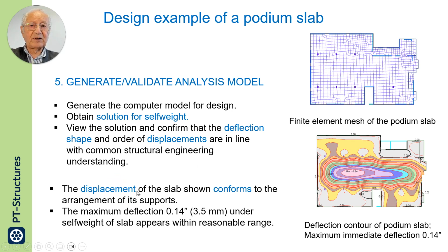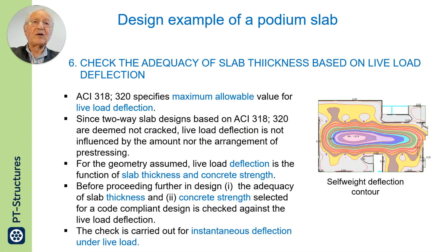The displacement of the slab conforms to the arrangement of its support. The maximum deflection is a reasonable number. At this time, I don't have live load and other loads, but I take the value and judge it against my own experience, whether it is reasonable or not.